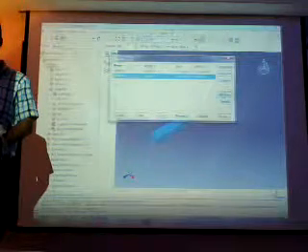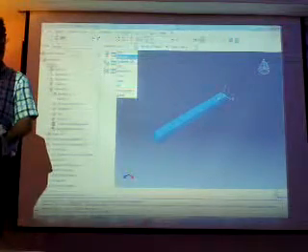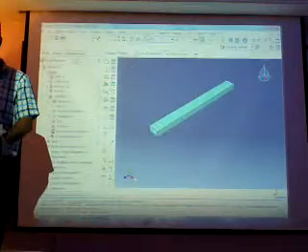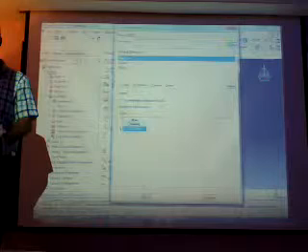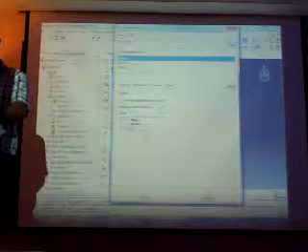These steps, you have only one step, so you need to have another step. Also, I think the problem is with the density. No, you have to take a ton per meter. Yes. You inserted already ton per meter? Ton per millimeter. So that will be minus 6.